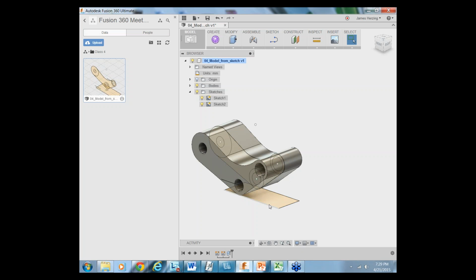All right, so now what are we going to do? We're going to create more geometry. So to do that, we're going to highlight our sketch. If you haven't been fiddling like I have, your model looks like this currently. Well, we want that profile back. Like I was saying earlier, once you extrude from a sketch, Fusion automatically hides that sketch. You kind of consumed it, so you don't need it anymore. Well, we still want it because we want to use it to change our geometry more. So I click on this little drop down next to sketches, and I click the light bulb to show that profile again. And so now I can see all of that sketch geometry still on my screen.